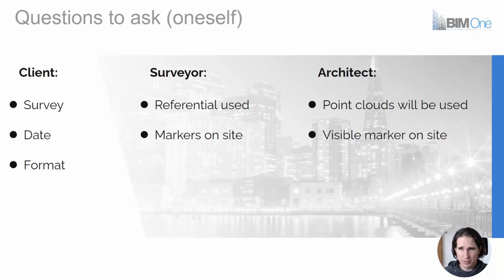And that's a critical question for their use, because of the insertion of the point cloud with respect to the internal origin in software like Revit, for example. You would have to take care of that from the very beginning if you don't want to mess up your project. We'll come to this in the second webinar, where we will explain how to use the local origin to make a point cloud work in Revit, whatever the possibilities you have.